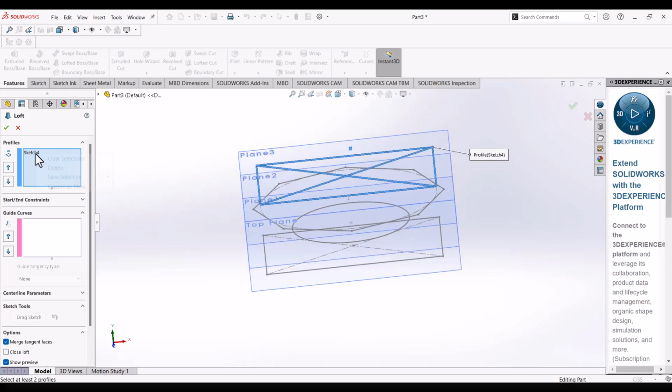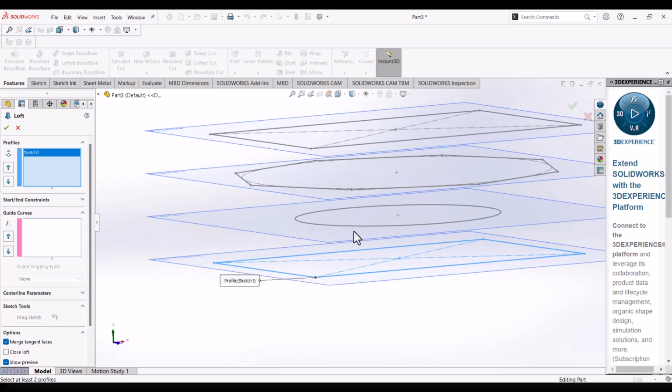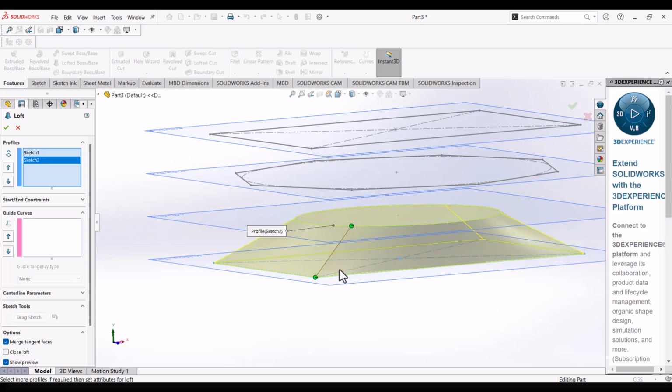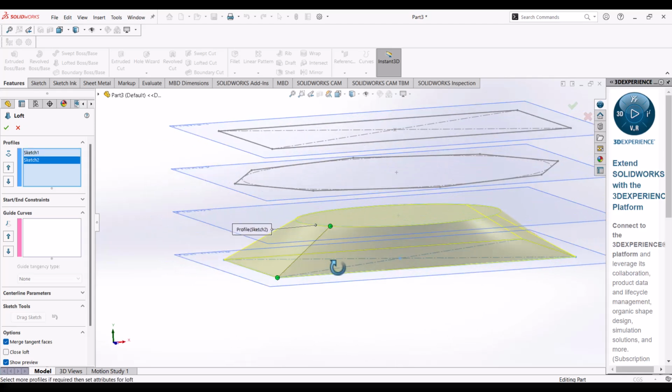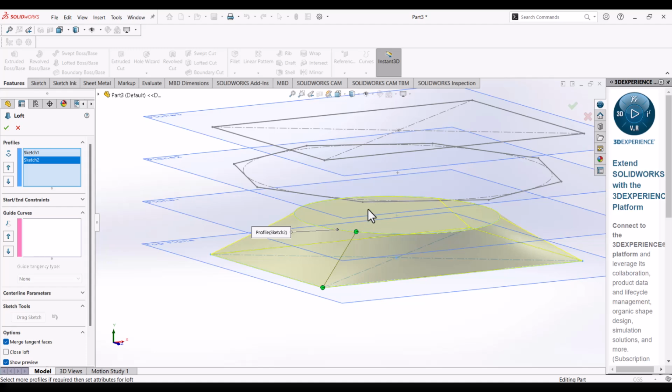Let me clear this plane. Clear selection. Now let me select this. Let me click on this edge. So I've selected this. No, the circle comes before. So I've selected the edge, the corner, the vertex of the rectangle. Now let me click on this circle. You see, it gives you a preview of how it will look. And then now let me move to the next one, the next edge. I click on this edge.